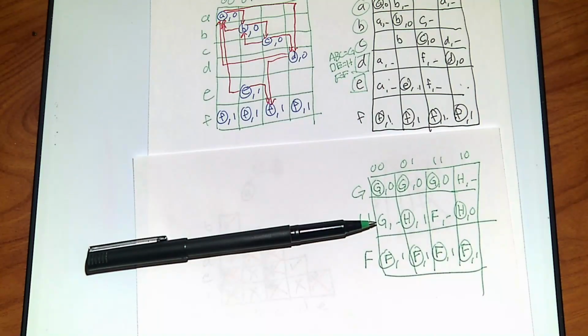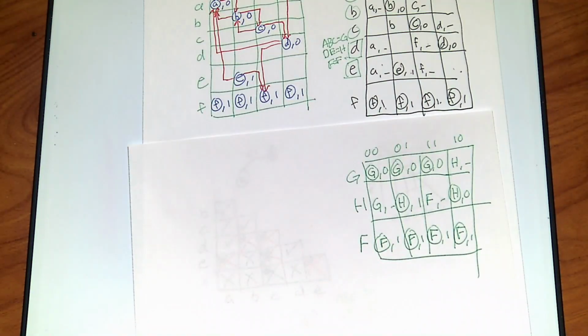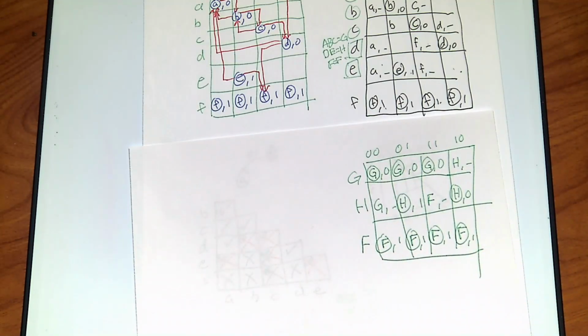So if I'm in H and it's 0, 1, you must output a 1. If I'm in H and it's a 1, 0, you must output a 0. It's unavoidable, right, that you get a Mealy. Does that make sense? Okay. So looking at these, now I have to go to doing some design. Now this is 3, right? So let's think about what ways could I encode states.